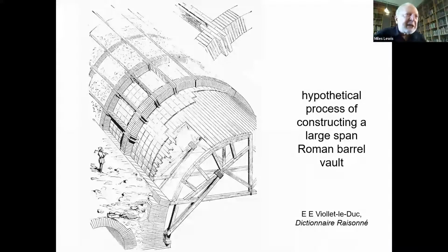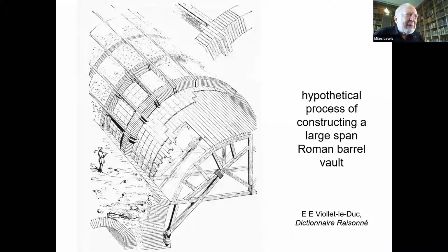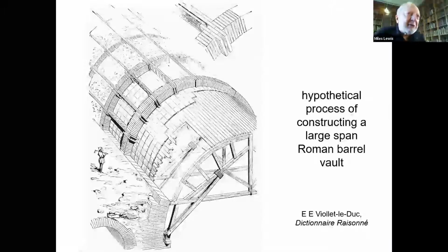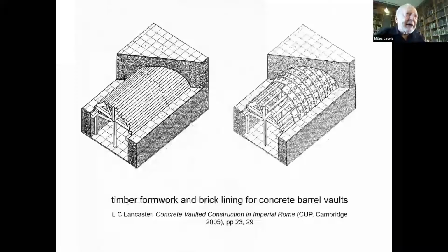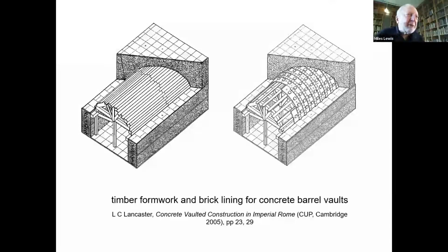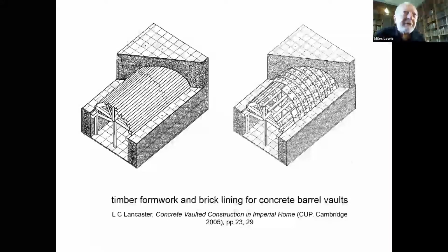In fact, this is perhaps an exaggerated version of the formwork. Formwork is expensive and difficult with early tools, with elaborate timber working, and often you place those tiles in a much more irregular timber system. It's a way of providing a true face for the concrete without having to build the timber accurately. There on the left, you've got a continuous formwork forming the concrete, but on the right, you see there's no continuous boarding. The tiles have been placed straight onto those slats to make the face of the concrete, I mean.